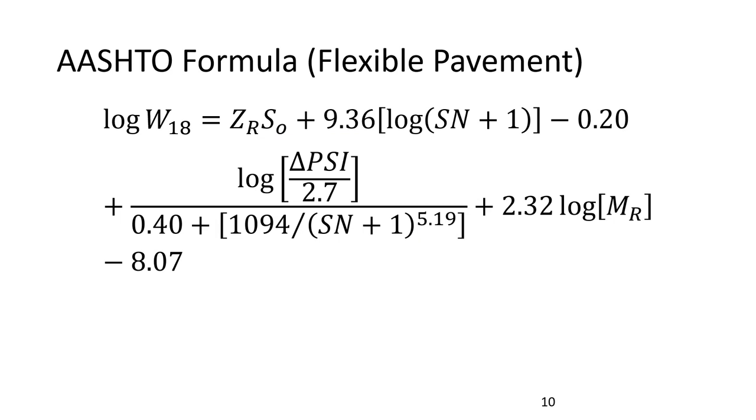All right. This is the equation for flexible pavement. Hopefully you remember it from before, right? Doesn't everybody remember this? It's crazy. This is a huge monster. It's held up over the test of time, right? They defined this back in the 60s at the AASHO road tests over in Ottawa, Illinois on I-80. In that area, they built those test tracks and tested all that and then came up with this. Log of W18, this is the standard log, not the natural log. This is the standard log of the number of 18-kip equivalent axles that have passed that road. So that's your ESAL number, right?